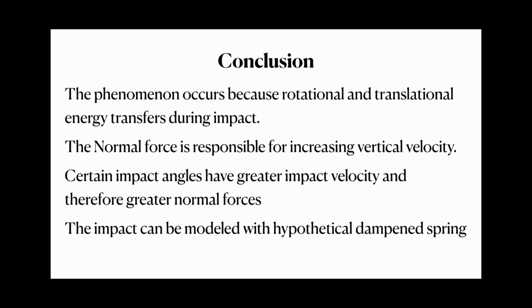So in our conclusion, the phenomenon occurs because rotational and translational energy transfers during the impact. The normal force is responsible for creating a greater vertical velocity. Certain impact angles have greater impact velocity and therefore greater normal forces. The impact can be modeled with a hypothetical damped spring.